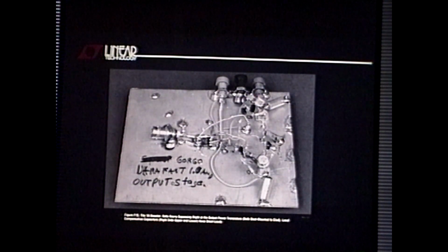This is the 1 amp output stage, okay, with the quasi-complementary bottom end in this thing. Here's the input. Here's the control amp right up near the input. I'm keeping my inputs as tightly wired as I can. Now the output stage doesn't really have to be that tightly wired, and why is that? Because it's a 1 amp stage and it operates at fairly low impedances. So whatever shunt capacitances there are don't have as much effect as you might think because there's lots of current flowing.